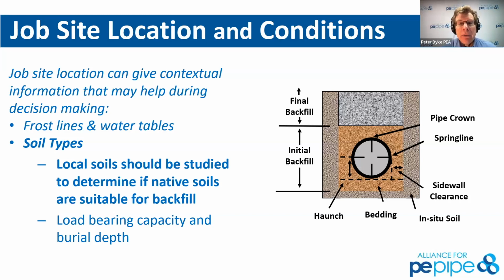The first was, hey, what do I do if I have sharp-edged rocks? Okay, so sharp-edged rock of that nature is typically going to be caught up during that reaming process as we're coming back through. It's that change in soil condition that's going to plague that reamer as it goes through. So they have different reamer types for varying soil conditions, which include rocks, cobbles, limestone, sandy soils, and other things.